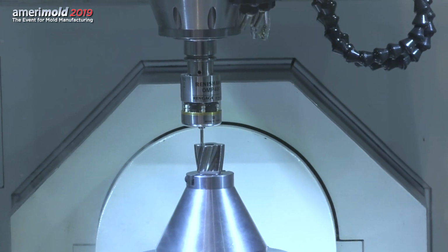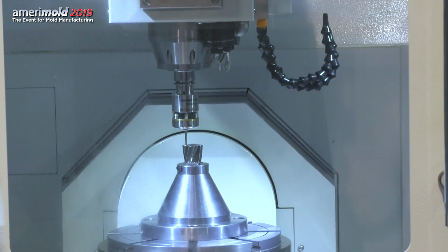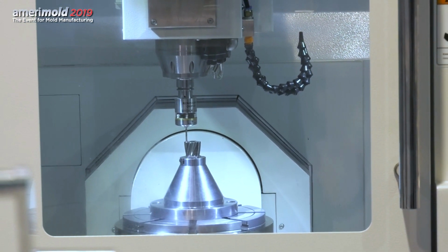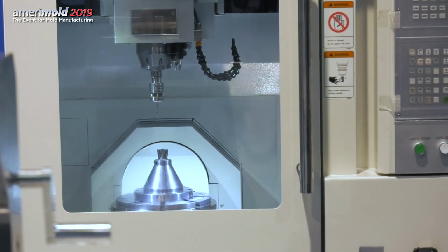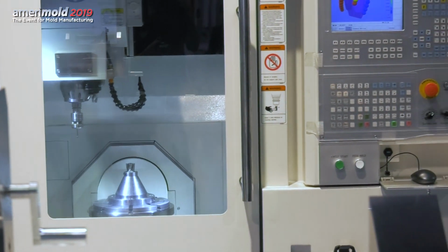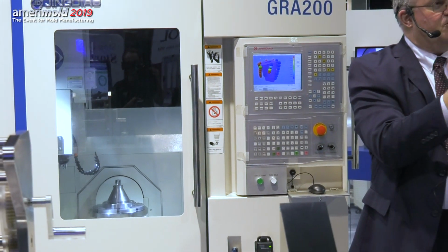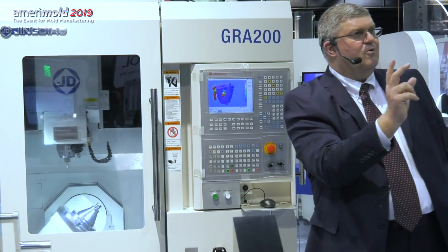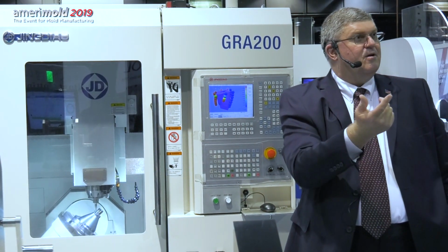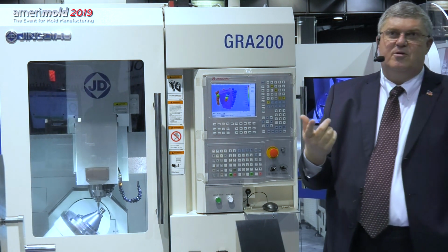Some of the applications that we do for customers, working on one for a U.S. manufacturer right now that to guarantee a particular location or a particular height, we'll go ahead and probe it. In some cases, orientation is critical, so we use a CCD system to look at the orientation, and then we'll make adjustments to the machine offsets to automatically follow through with that.